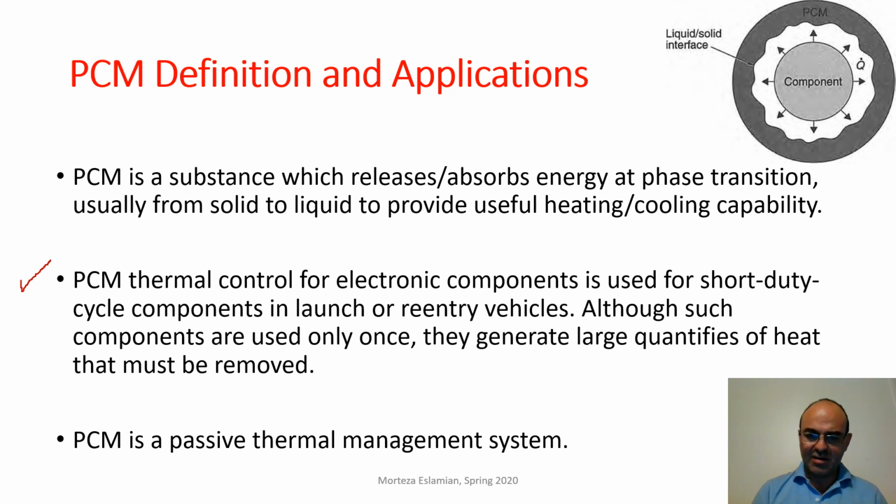And phase change materials are usually used during this stage because they can absorb a lot of heat in a short amount of time because of the phase change process involved here. Using phase change material is a passive thermal management system, so it is reliable because there is no moving part.